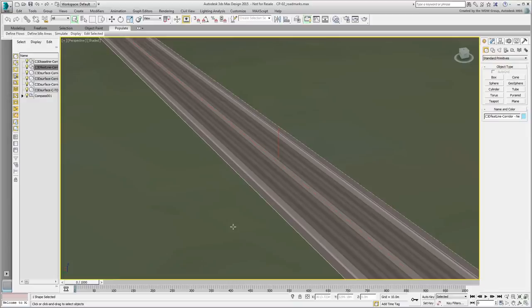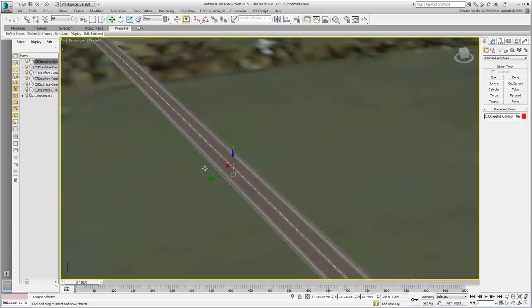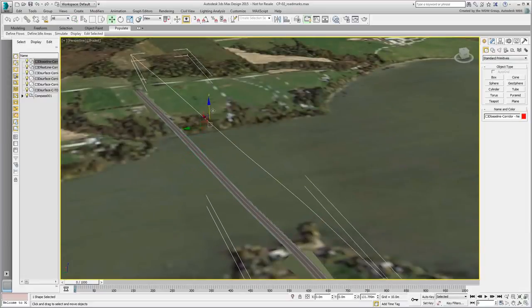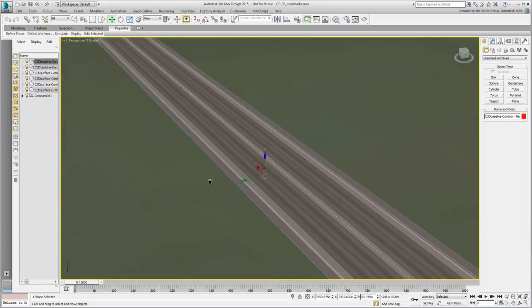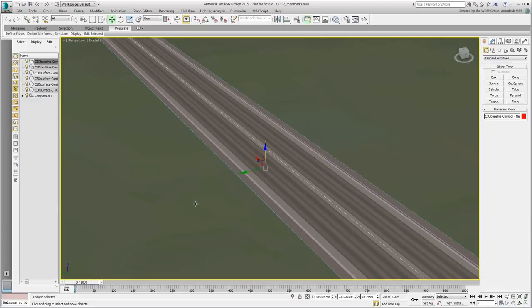To create road marks in Civil View, you need the reference spline first. Fortunately, you already have one, courtesy of the centerline alignment you imported from Civil 3D. Go ahead and select it. It should be the first item in the 3ds Max Explorer, and runs along the bridge design from beginning to end. Also, make sure that Civil View Explorer is docked to the left.